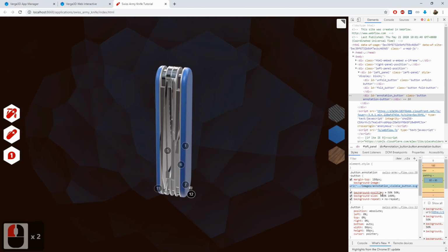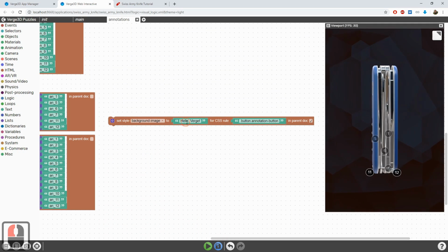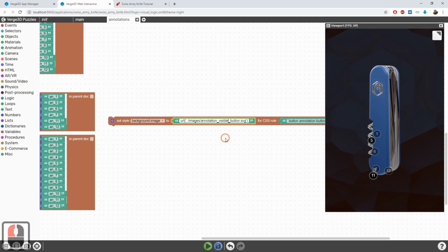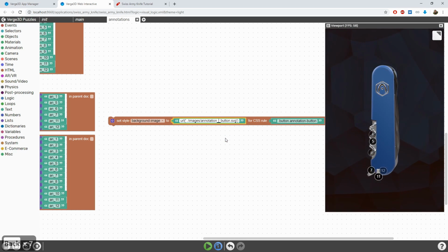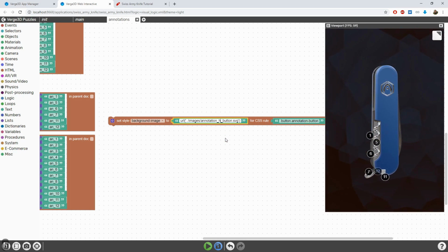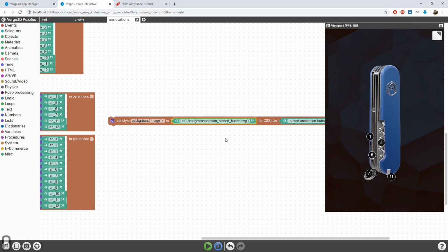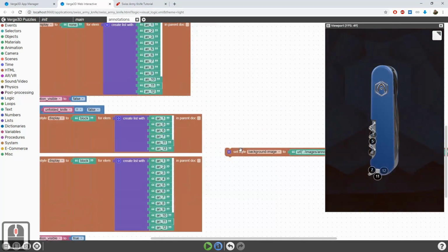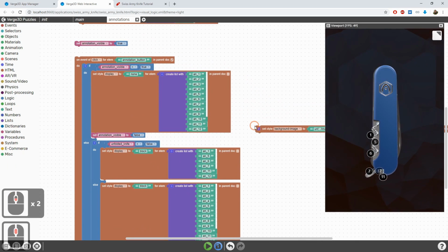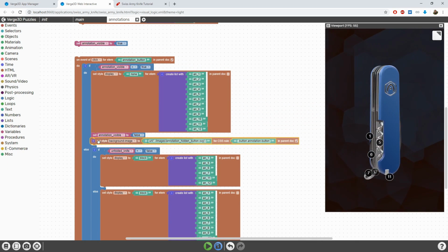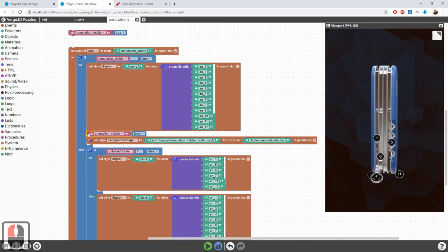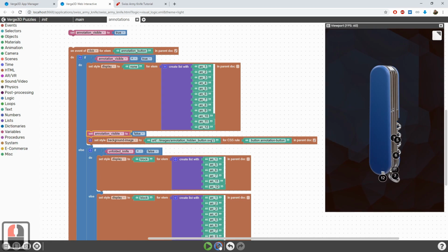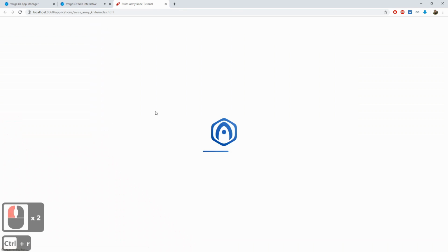And copy the path to the icon which is currently assigned to our button. Let's just fix the image file name because our new icon has hidden in its name and it's the only difference. Now place this puzzle near the variable where the state of annotations visibility is changed to false. Let's save the puzzles and check out the app.